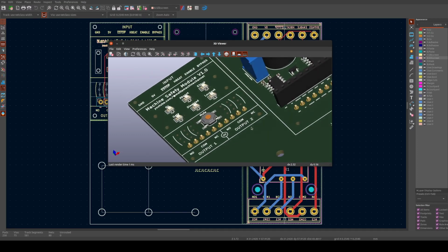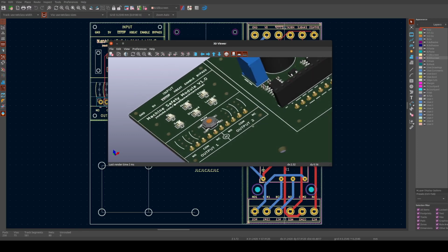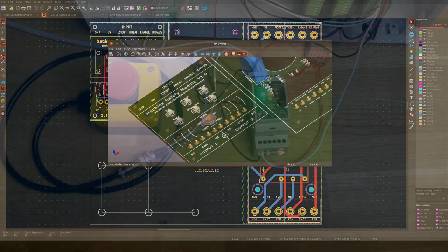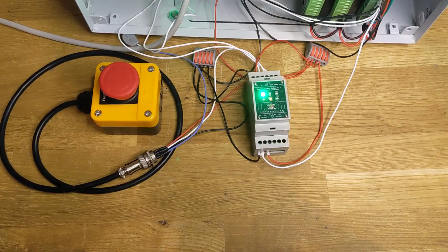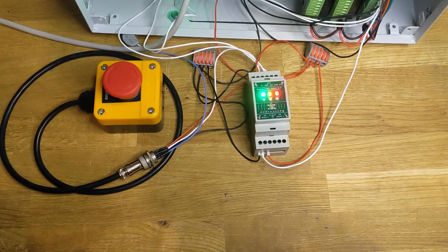I also didn't have one of these surface mounted switches to test with, and there is a bit of bounce in it that makes it quite difficult to correctly interact with the toggle mute circuit. Neither of these issues are really critical, and the module otherwise works correctly in every way.